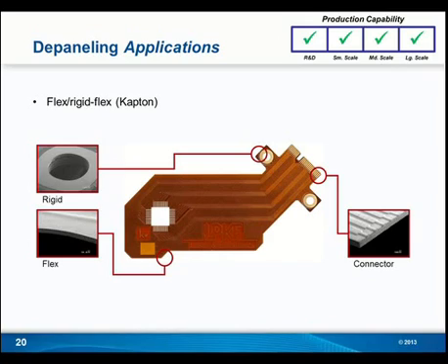So you can set parameters for the different materials in the same job, and then you do not cut, let's say, the polyimide with the same power you would cut copper with, and you do not damage it in any way. So you can see there's no thermal effect on the material at all on the polyimide side, but then on the copper side, you still have enough power to cut through it. So this is really a great application for UV lasers, and it's definitely a large-scale application.